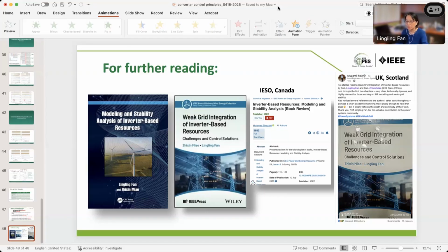But of course, in real world operation, you have lots and lots of options to do that. Sometimes it's Q priority, P priority, whether we want to do the reactive current first or the real current first. So lots of options. We don't cover that here, but people can refer to industrial documents like WECC modeling. You have lots of selection options to choose from as well.